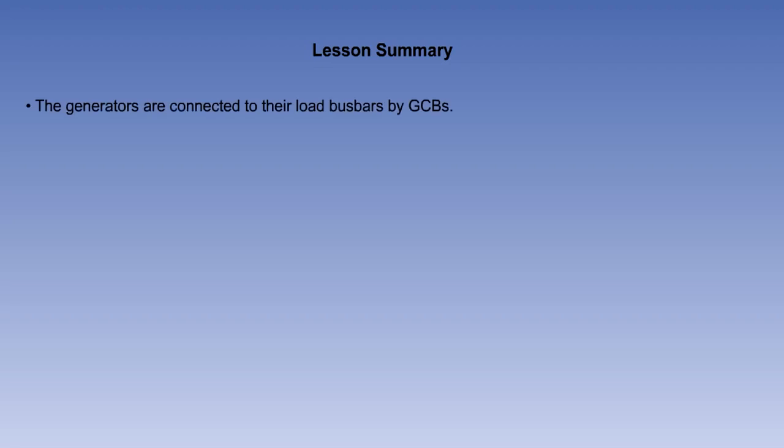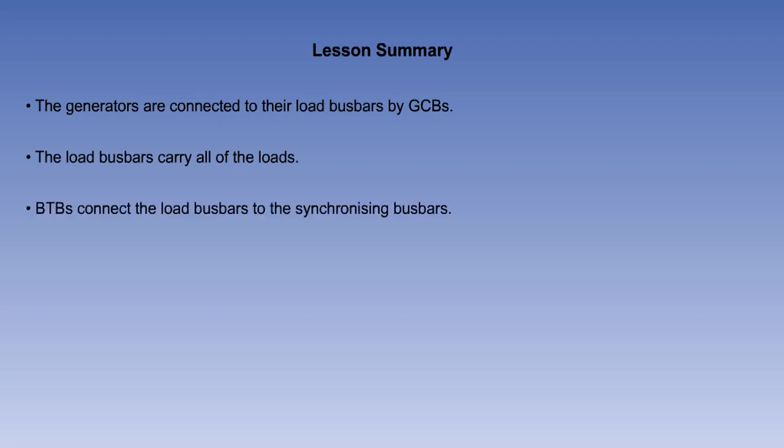The generators are connected to their load bus bars by generator control breakers. The load bus bars carry all of the loads. Bus tie breakers connect the load bus bars to the synchronizing bus bars. The synchronizing bus bars are connected together by the split system breaker.